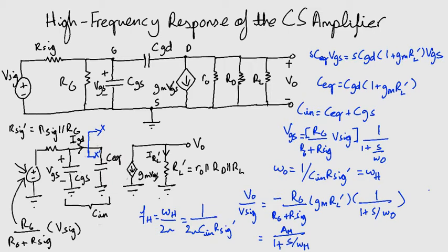Now notice the right side of the circuit is not a single time constant low pass or high pass type. It is simply a parallel combination of a voltage controlled current source and an effective resistance lumped together. The time constant arises in that part of the circuit which has capacitances.